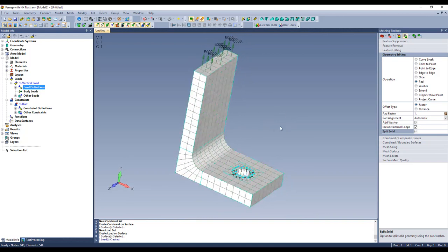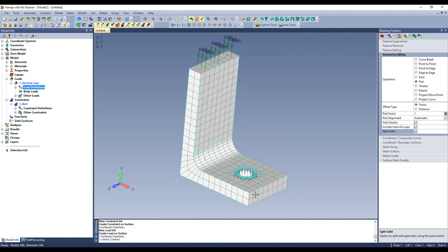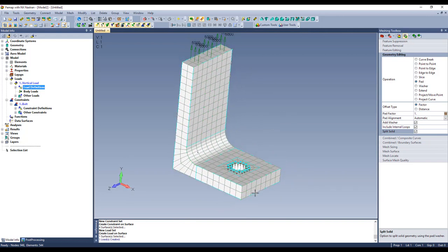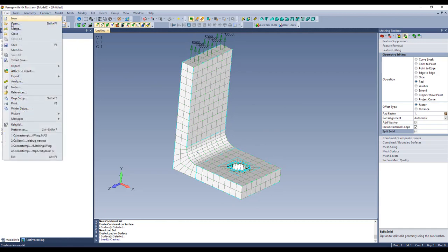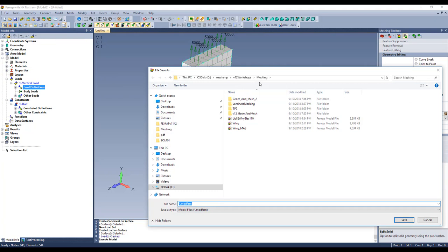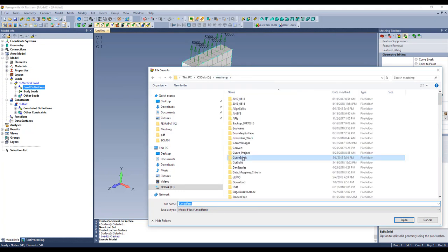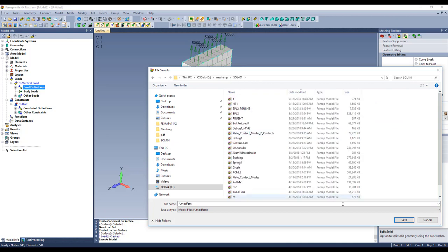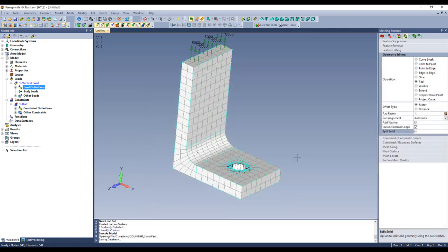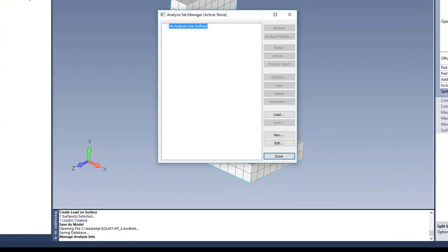Now let's just do a simple linear static run, without the heel and toe effect that we're going to model. What I'm going to do right now is save this. I've been saving these in a new file, because we'll run solution 401 in a minute. So we'll do heel toe 2. All right, he saved. But let's just run a static analysis without the heel toe effect.